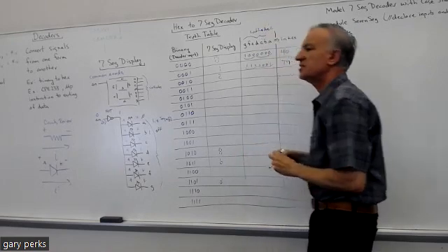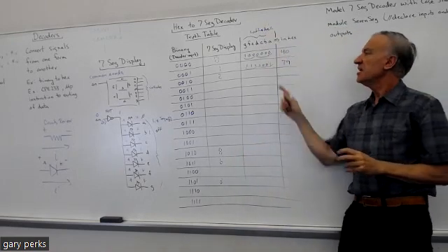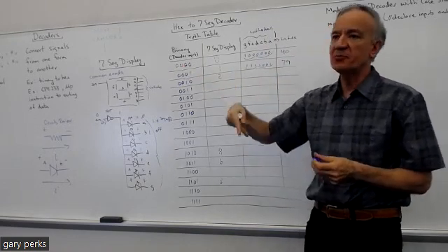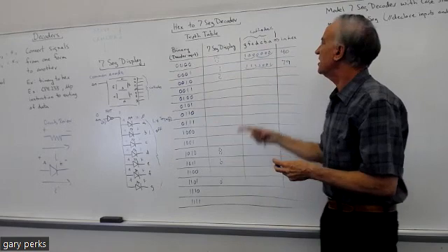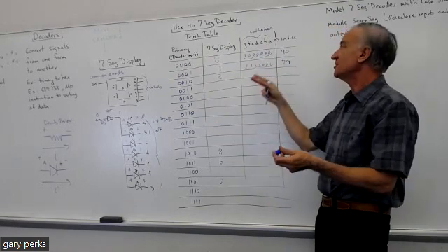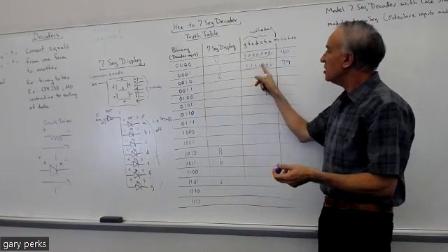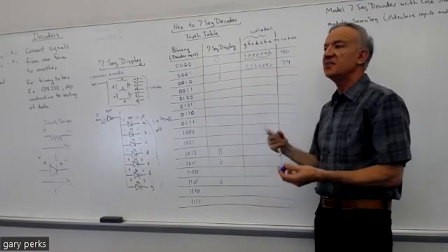All right, so you see, you're getting some review of things we talked about earlier. And again, this shows you why hex is a popular base in digital, because instead of saying 1 0 0 0 0 0 0, I can just say 40 hex. Instead of saying 1 1 1 1 0 0 1, I can say 79 hex.